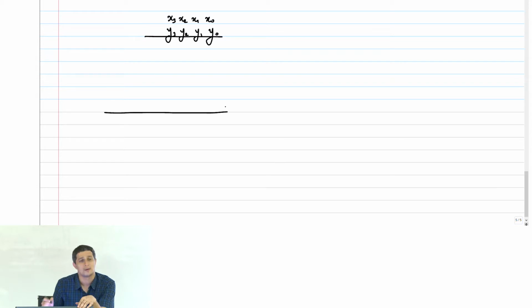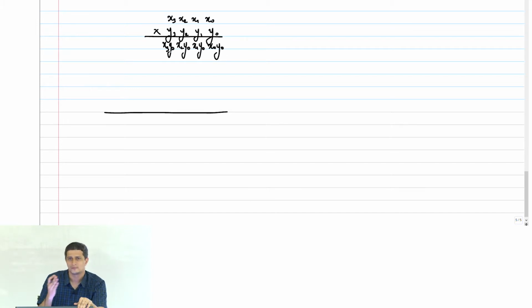So now let us see what we have to do. Suppose I take x3, x2, x1, x0 and y3, y2, y1, y0, and I tell you both these numbers are 4-bit 2's complement numbers. The first row is x0y0, x1y0, x2y0, x3y0. Then I shift and add.